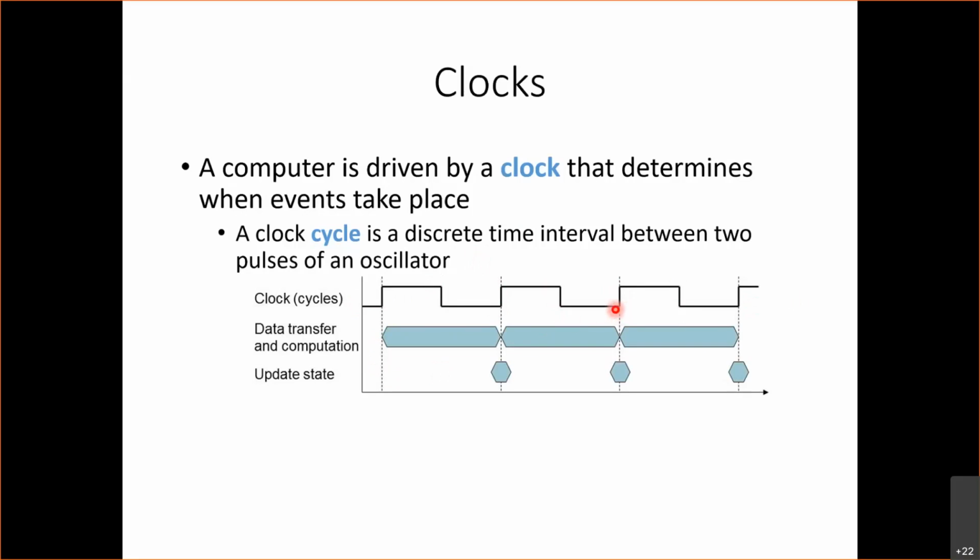of this clock cycle, you can see here you have a clock. We call this a clock edge. So this entire pulse of the clock, we call this one clock cycle. And usually the way that computers work is in between edges of the clock cycle, in between pulses, we do some work, and then on the clock edge, we update some data in the computer based on the work that we did throughout the clock cycle.